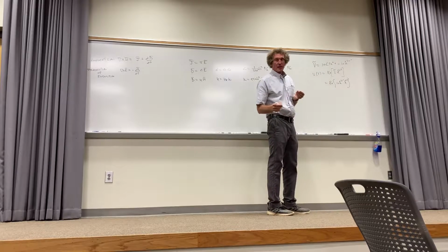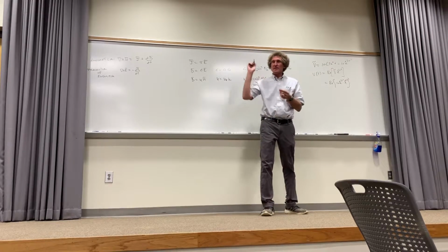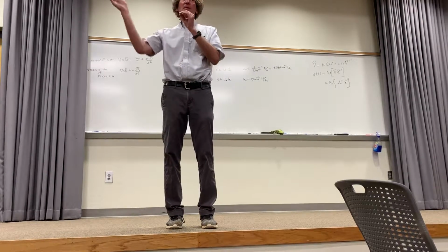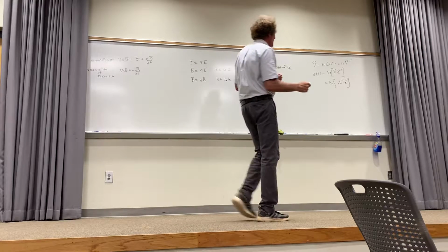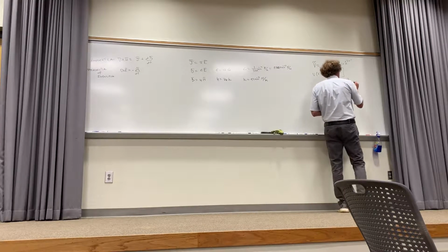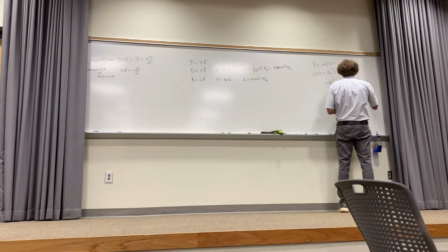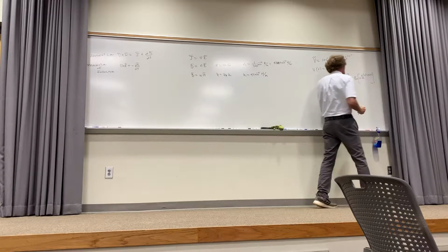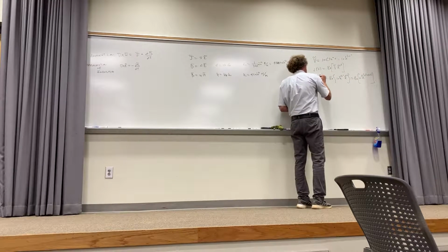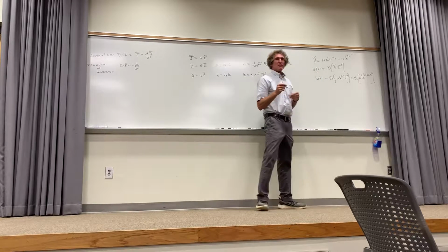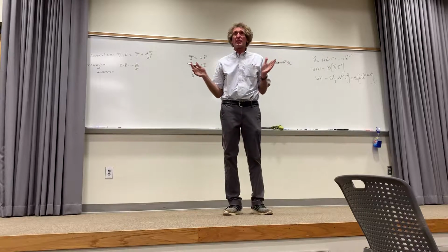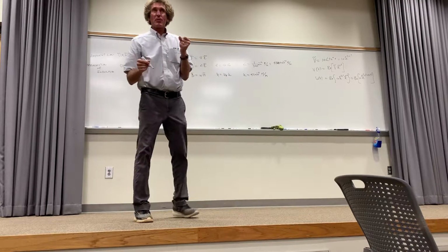Now, if you have e to the a and e to the b and you multiply them, that's really e to the a plus b. You add exponents. So this is really the real part of 10 times e to the j, omega t plus 30 degrees. And that's the voltage, V of t. I'm going to go a step further. After that, I can say the real part of any of this can be found very easily. By the way, does everybody understand when I say real part of something, what it means?